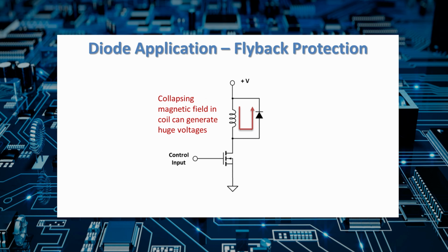And that's how flyback transformers in old television sets used to work. They were able to generate 25,000 volts from the 120 volt input. In fact, most boost converters, where you see a 5 volt to 30 volt boost converter, work that same way on the flyback effect. It's extremely important that whenever you have an inductive load, a coil or a motor, that's being controlled by a transistor, you need to put a flyback diode across that coil, or you will burn out your transistor almost every time.